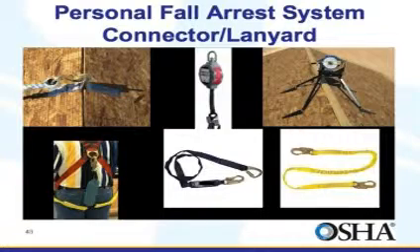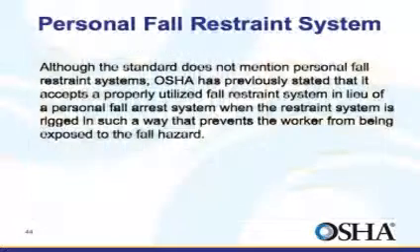Self-retracting lifelines and lanyards, which do not limit free fall distance to 2 feet or less, rip-stitch lanyards, and tearing and deforming lanyards shall be capable of sustaining a minimum load of 5,000 pounds in the fully extended positions. Ropes and straps used in lanyard lifelines and strength components of body belts and body harnesses shall be made from synthetic fiber.